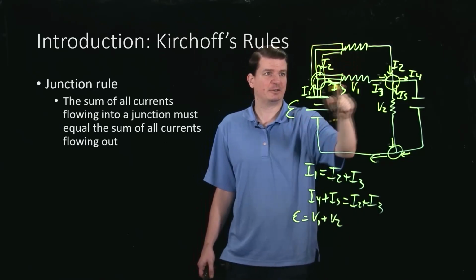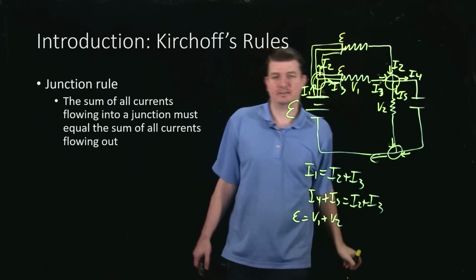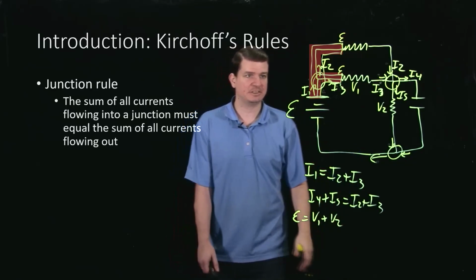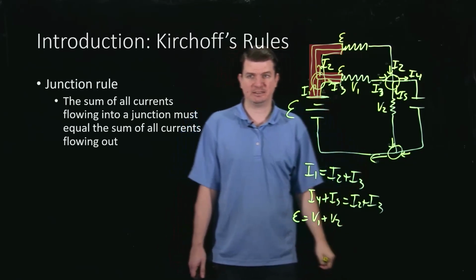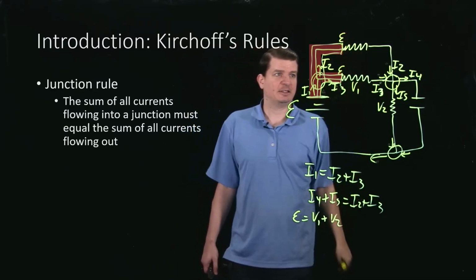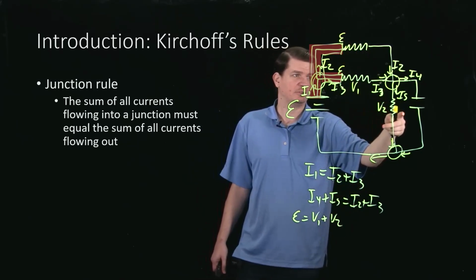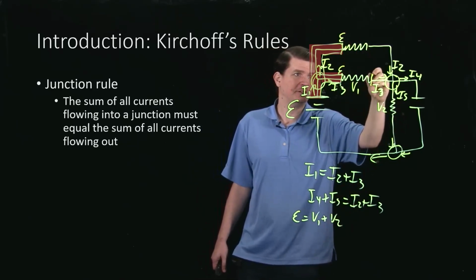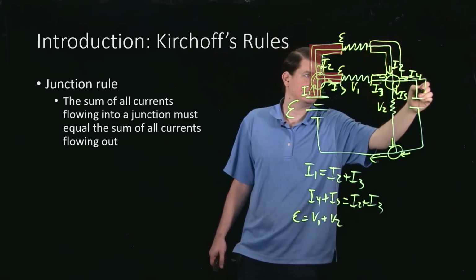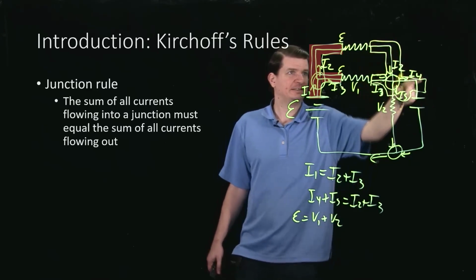So we know that right up until here, if this thing is a positive EMF, then those things are at the same potential, which is equal to the EMF of the battery, say, because we're not worried about the internal resistance. So these things are sitting at the EMF. Then there's some drop across here. There's another drop across here. So this bit all is going to sit at the same potential because it's all a conductor. So all of that's at the same thing.